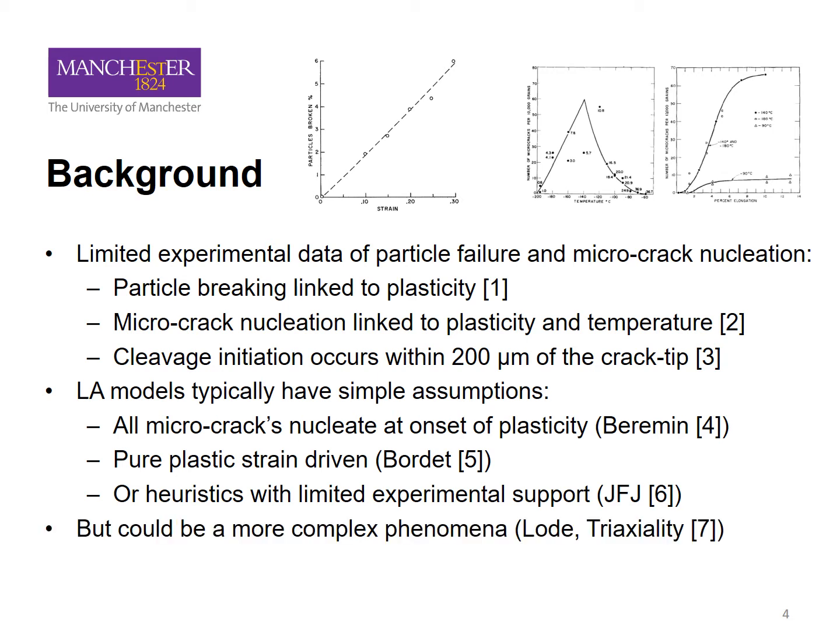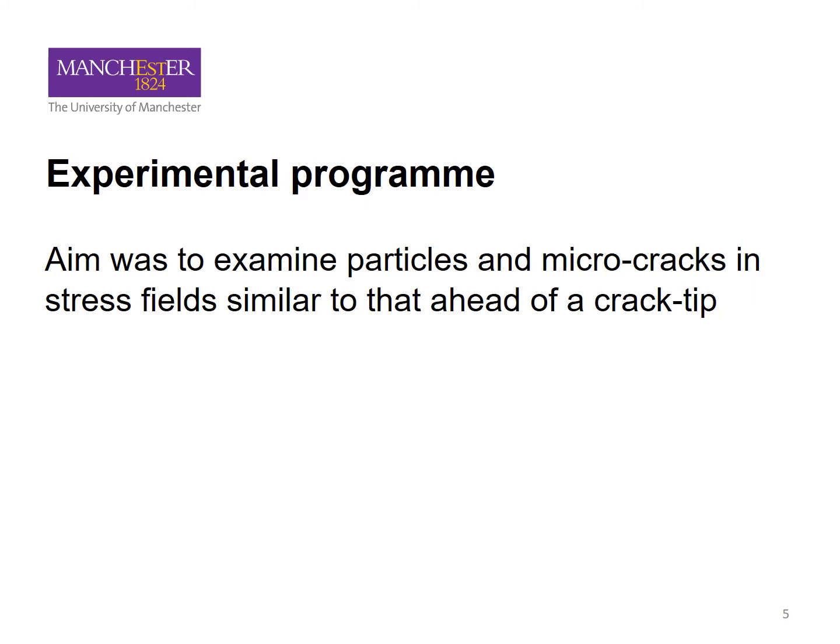So these are really quite simple and the experimental data is quite limited, but we think it should be a more complex phenomenon, including things like the Lode parameter or triaxiality possibly. We want to capture the full stress field and the effect of the full stress field, not just maximum principal stress or plastic strain. Therefore, a small experimental program was designed to try to examine particles and microcracks in stress fields similar to those ahead of a crack tip.